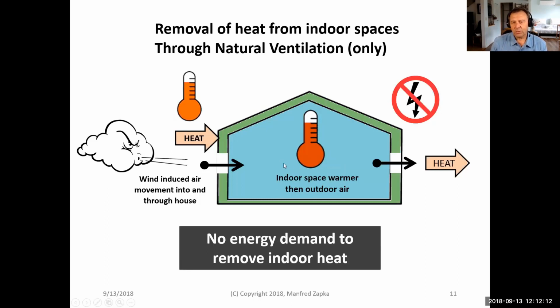So wind goes through here, takes out the air which is inside, replaces it with outside air, and gets rid of the heat. But usually by doing this alone, the indoor space is always slightly warmer than outside. So there's a limit to how much heat we can remove. But the big advantage is that we do not use any energy to remove the indoor heat with natural ventilation.